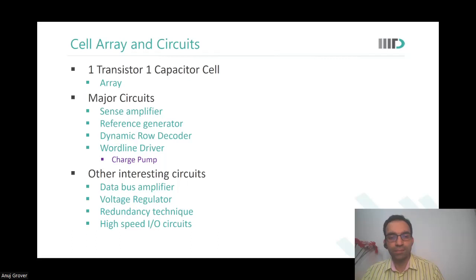Sir, is word line overdrive done only when VINT is high? Like, if a one is stored only, then word line overdrive is done, or is it done for all cases? So can you tell that in a particular row you will store all the ones, or do you think there would be zeros? If it is a common word line, whether you are storing a 1 or a 0 doesn't matter. The word line is being overdriven. So what does that do? That ensures that you can keep M1 smaller. So you keep M1 small, you save area. Yes, sir. Okay.